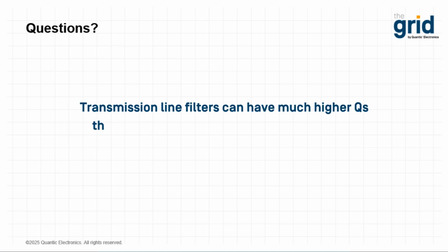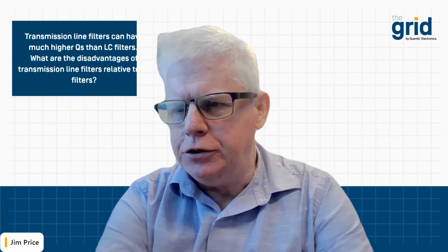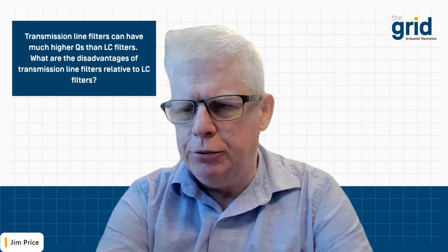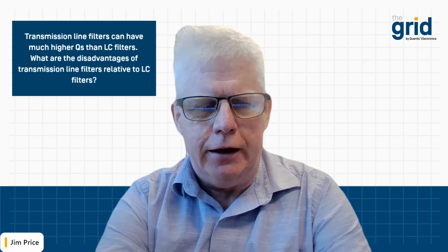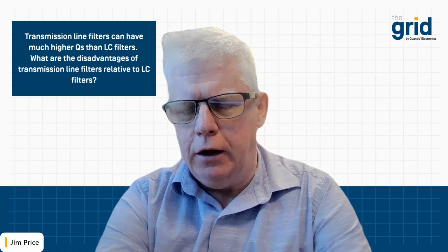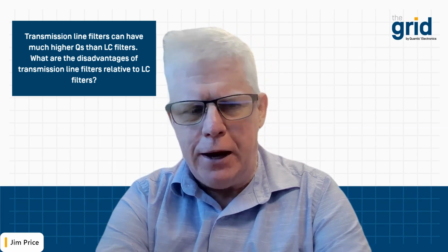Transmission line filters can have much higher Qs than LC filters. What are the disadvantages of transmission line filters relative to LC filters? There are a couple disadvantages. The one, as I had mentioned in the presentation, is that they tend to repeat over frequency. So transmission line filters will resonate and re-resonate at higher frequencies. So you'll get additional pass bands beyond your original lower frequency pass band. And a lot of times that's very undesirable.